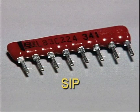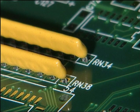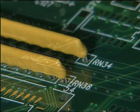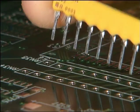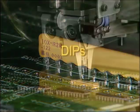SIPs consist of a single row of leads and are often resistor networks or diode arrays. The reference designator for a particular SIP is based on the function. Resistor networks will usually use R for a reference designator, and diode arrays will use a D or CR. In many cases, a dot or number will indicate pin 1 for orientation.